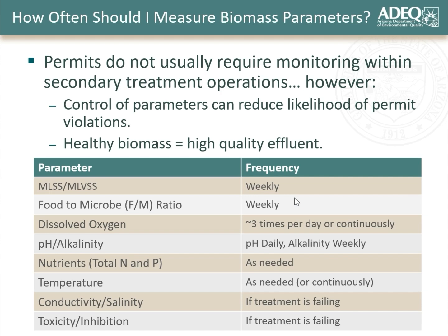So we've got a list of generally recommended frequencies we'd have for testing things. Once again, each facility is different, and so I would consult and think about how your facility operates and your resources too. But this is a baseline in terms of what we'd recommend for the frequency of monitoring things like your mixed liquor suspended solids concentration, your food to microorganism ratio, and whatnot. So just something to think about.